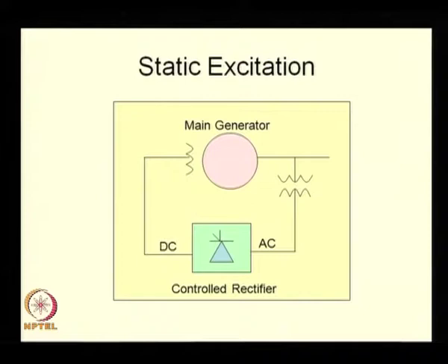cause some field current which will enhance the existing residual flux in the machine. You will find that the voltage increases, and some kind of a positive feedback mechanism will ensure that the machine self excites. Okay. So, this can actually happen in a practical situation, of course, because you require adequate residual fluxes to generate initially an AC voltage which will forward bias the thyristors.